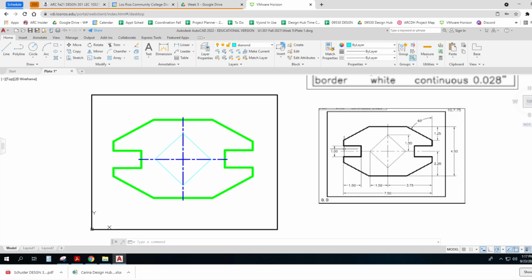This is a rectangle, 1.5 by 1. I tend to do that, although I could have just drawn over 1.5, up and over and trimmed out 2. Would work just as well. So it's kind of cool. These, I knew that these corners were 1.25 away, and I chose to do the O snap command.